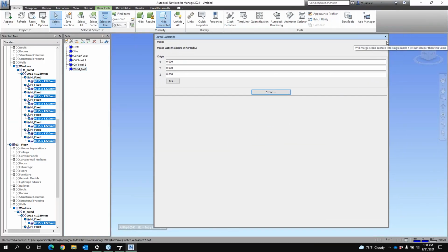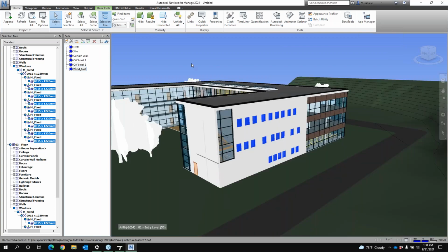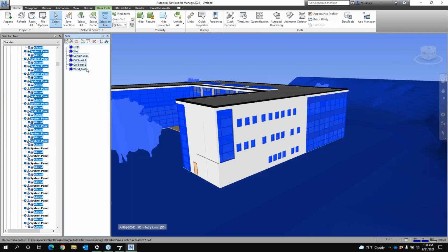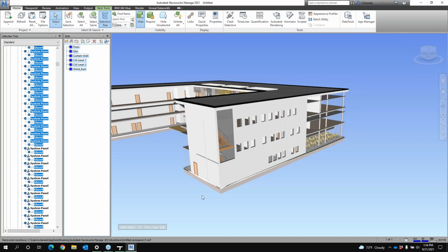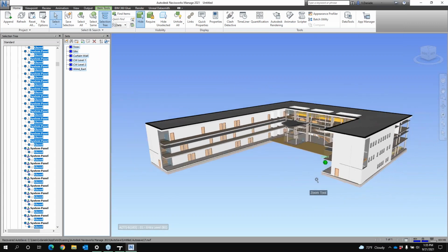So in going through this in a really large project, using some of the tricks for Navisworks to split the model up, the thing you do have to be careful of is, if I do an unhide all, and then I want to export most of the building minus my selection sets, you want to make sure that you grab all of your selection sets and hide them before you export. Otherwise, you're going to get double objects when you go to export. Or even just selecting the inverse. But I find this is really the way to go if we're trying to split the model up.